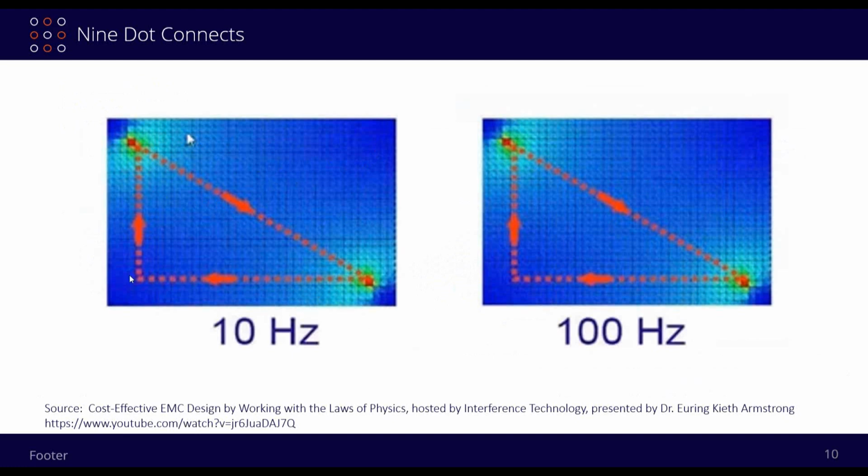So they also drew in these lines. These lines over here are just drawn in for reference points. This point over here is where it enters into the board after the line has been hovering above for 2 centimeters. And this is where we're actually energizing with our AC voltage. So we go from all the way up here, and then we energize the circuit. It's going through the line over here. It's going back down to the board. And the question is, how is it returning back to point A?